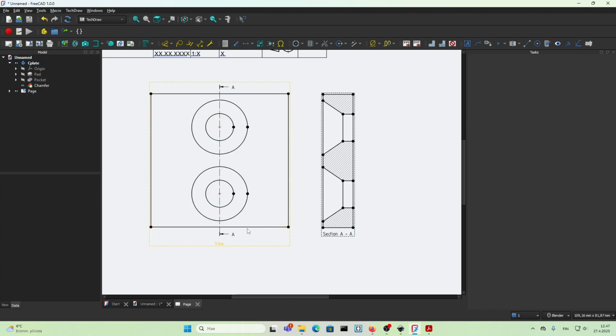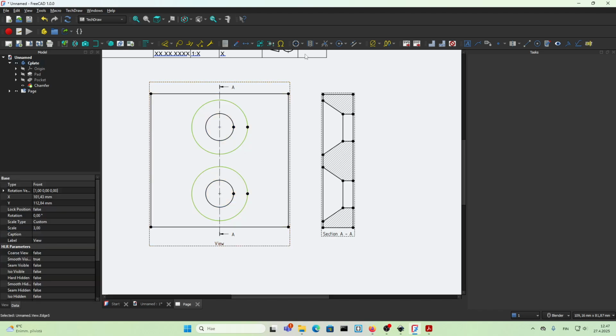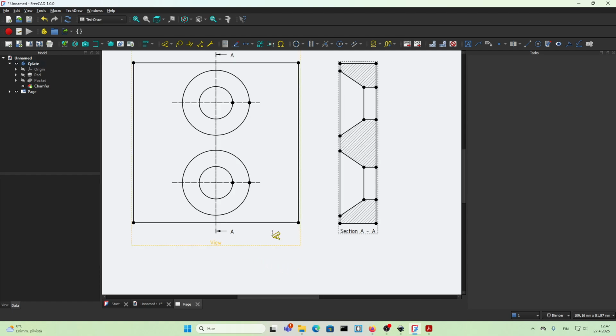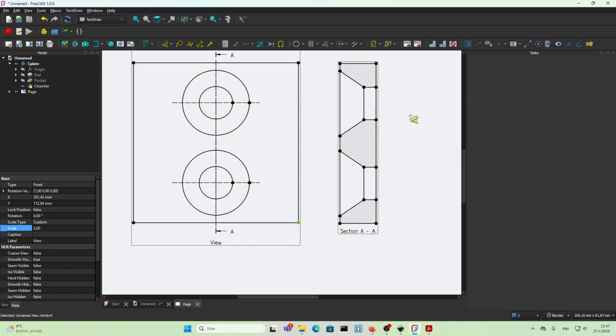Then let's add the cosmetic circle center lines. I will click on this. I will click on this, and from here we can add circle center lines. Now we have the circle center lines. Dimensions, D from the keyboard. From this dot, I will go from this dot to the center.